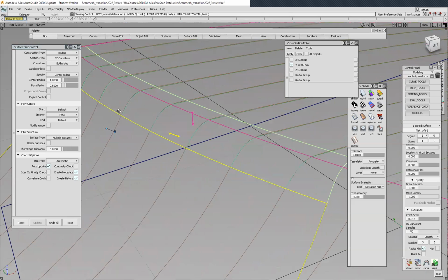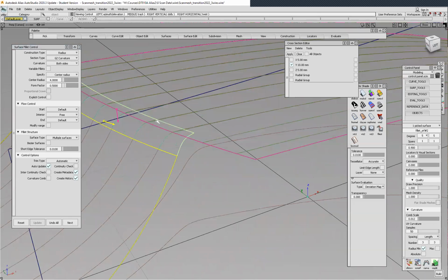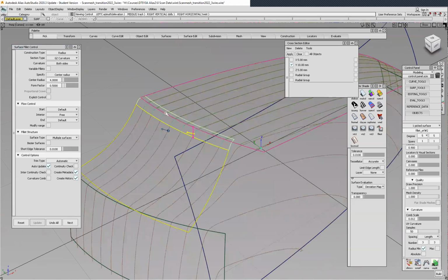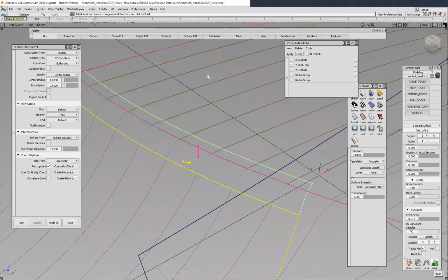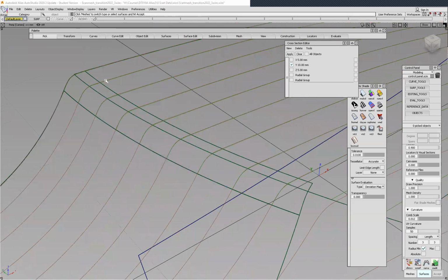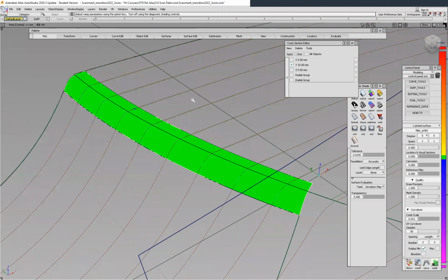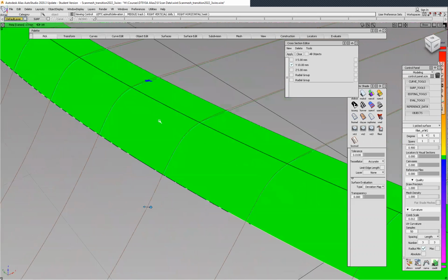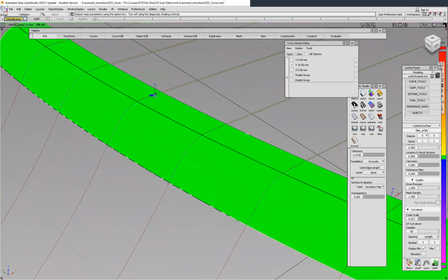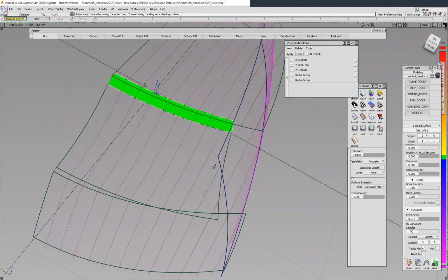Something like that. It looks like we're well within the limitations here. Let's check that one as well using the deviation map. So I click the surface, the scan data, and it's all green. So it should be good. I think I saw a tiny red or blue spot there, but that's just probably an error in the scanning. So I'm going to keep that one.